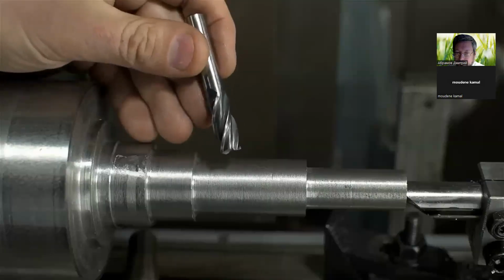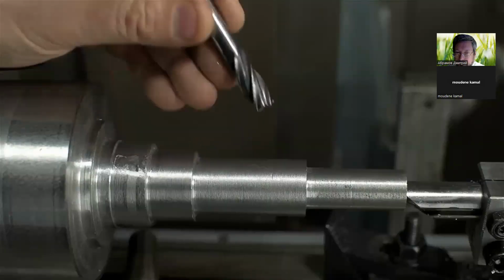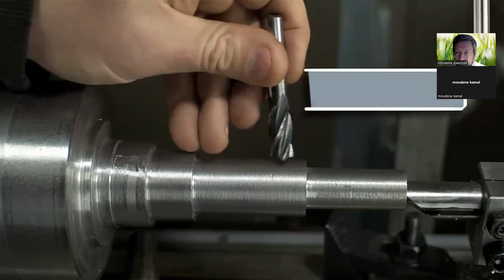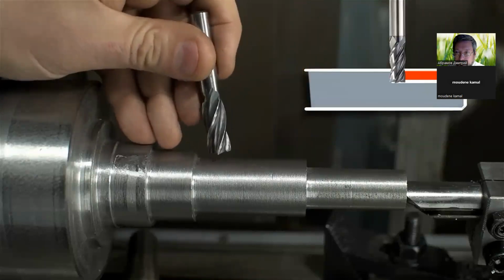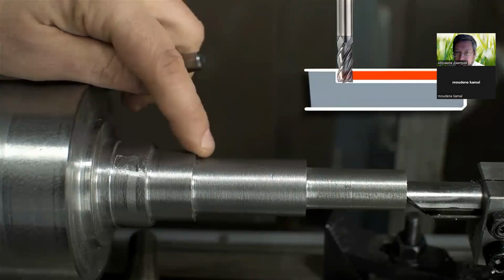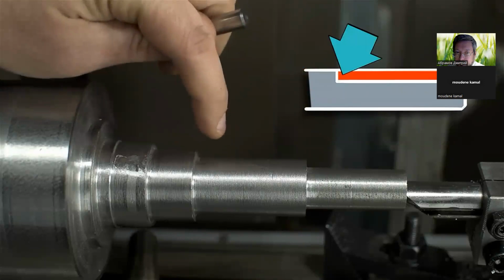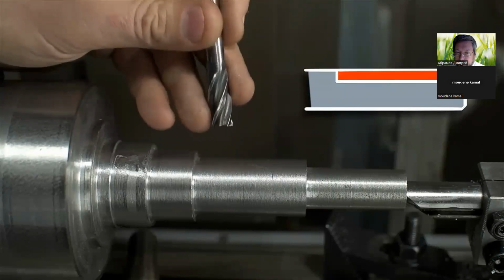You might be wondering why I'm not using just a regular end mill for this, and that's good. I briefly considered the same thing. Using a regular end mill like this to cut the splines would result in an abrupt end to that feature. Like where it stopped, it would look like a key seat in a shaft, just like a sharp inside 90-degree corner.